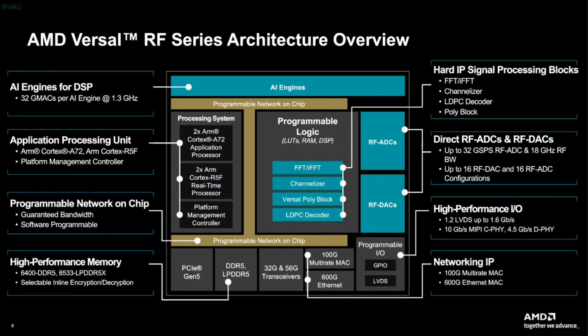So we'll leave the Zynq UltraScale Plus behind. Now the Versal is, let's call it, the next generation from AMD's adaptable SoC product line, and it went from the 16 nanometer node to a smaller node, typically 6 or 7 nanometer. And the architecture is different. The programmable logic's a little different. We have a different DSP, we call it a DSP58.